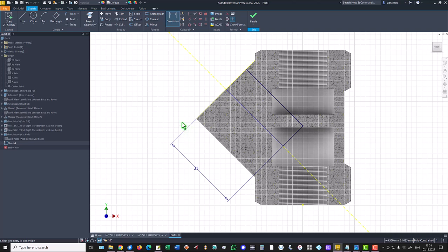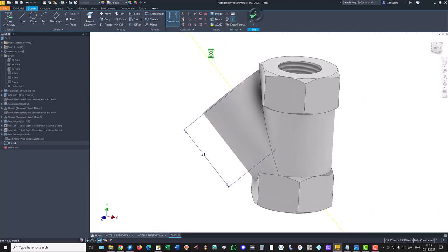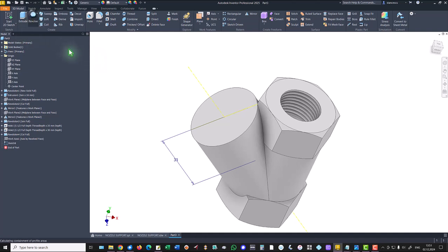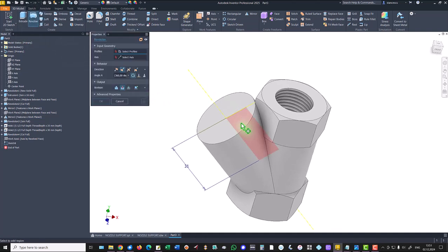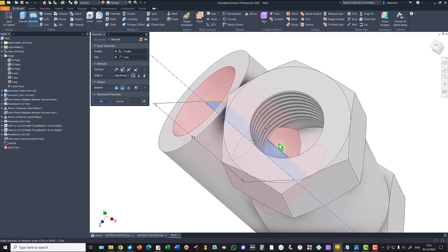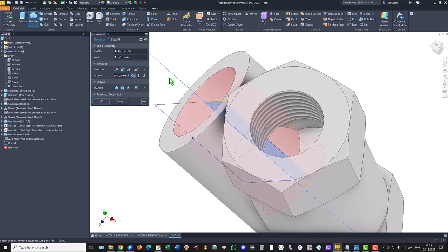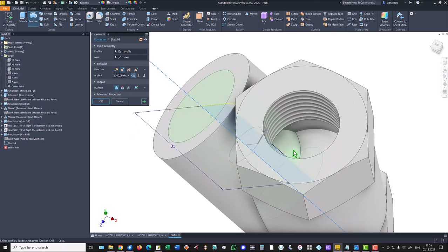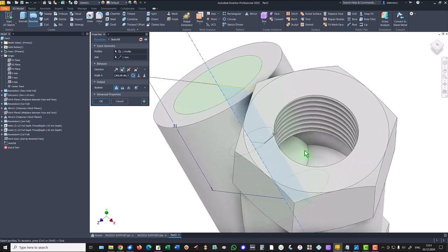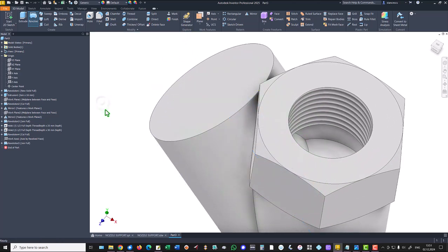Okay. Finish sketch. Revolve this. Then we select this axis, but not cutting anything. We select join to create this wall. Yes, this is why. Okay.